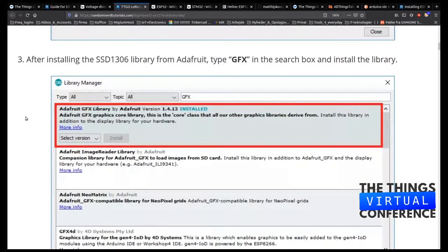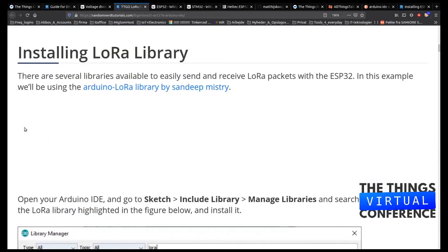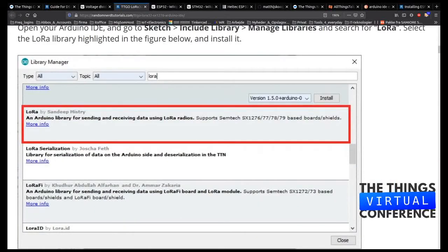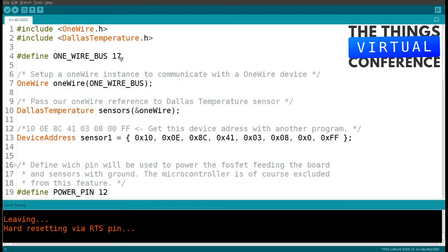So you can install it via the Arduino IDE library manager, or you can download from GitHub and then put the libraries in there equally to the other libraries, and then call them in the software with this include something there. And in C/C++, the .h file has all the stuff, or references all the stuff you need from the library. So you will not include the .cpp file. You will always only include the .h file in these libraries.